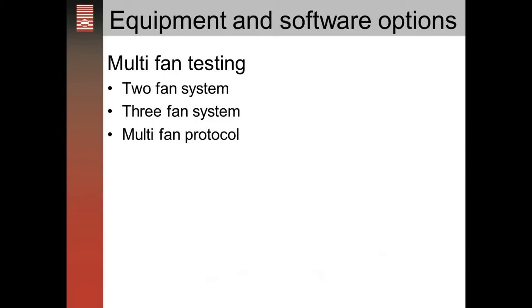You'll crank the second blower door up till you get to 50. Once you're at 50, you'll take the readings on those two, maybe set them to a long-term average, and once those numbers are pretty steady, then write down your blower door reading. So pretty simple protocol.